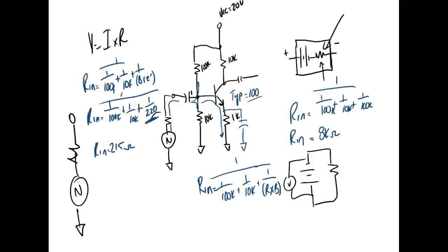So normally we go through 2 or 3 stages of amplification. The first one, we're looking for a high input resistance, so it won't load the signal source. In fact, later on we'll see that normally we use an FET there. So normally your first amplifier will be an FET amplifier because it has extremely high input resistance.